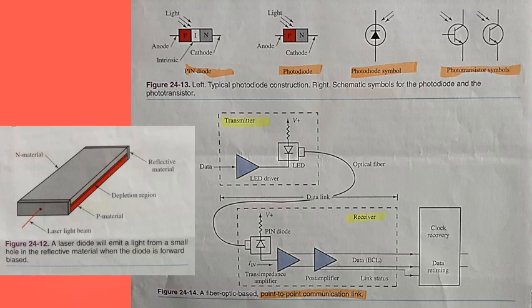Troubleshooting fiber optic systems. Troubleshooting fiber optic systems is as unique as the system itself. Two basic components are needed to troubleshoot the system: a light transmitter and a light receiver. The transmitter can be of LED or laser type, depending on the characteristics of the fiber being tested. LEDs with a wavelength of 850 to 1300 nanometers are generally used as the source. For a visual inspection, an LED at a wavelength of approximately 650 nanometers, red, is used.